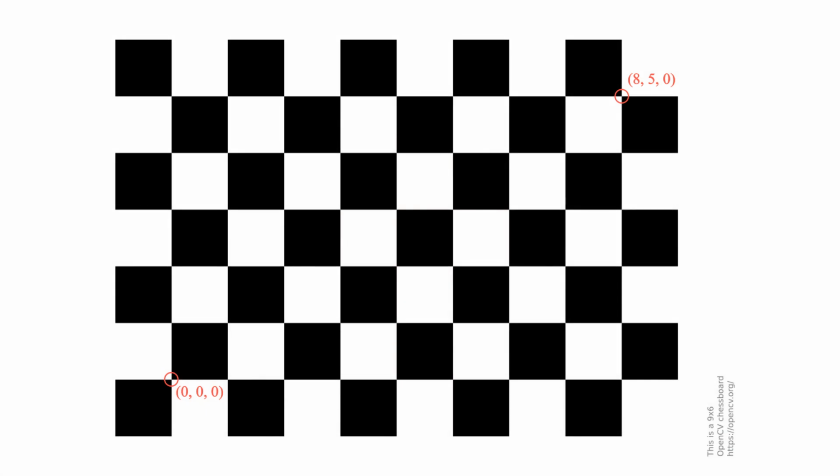The way in which the algorithm works is that it partially fixes 3 of the coordinates of the pattern on the target. OpenCV automatically chooses the first and last points of the pattern. We have to specify the third point, and OpenCV recommends to use a corner point of the pattern. So using this calibration method instead of the default one will give us more accurate results.